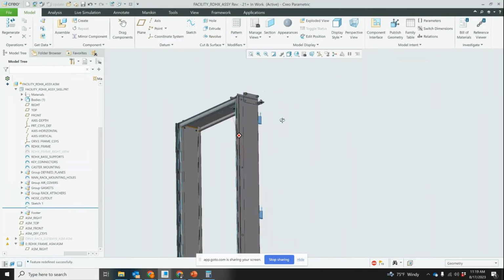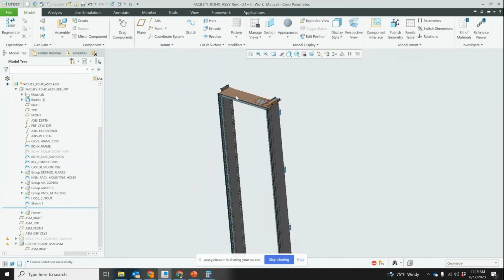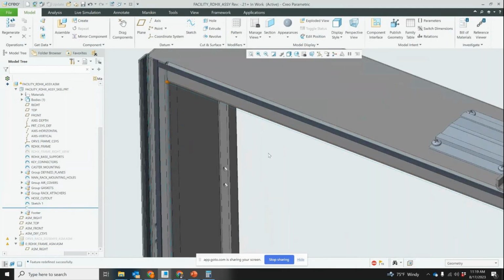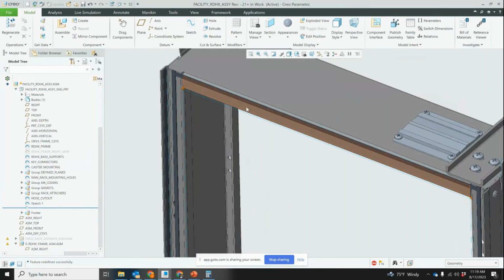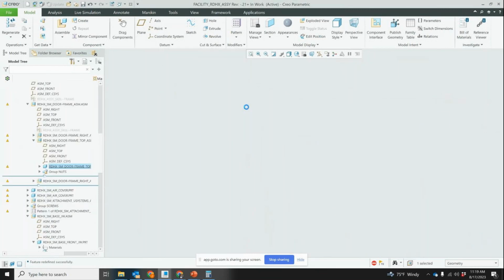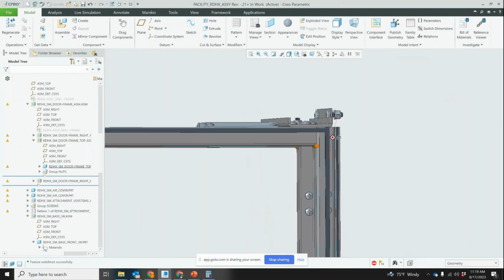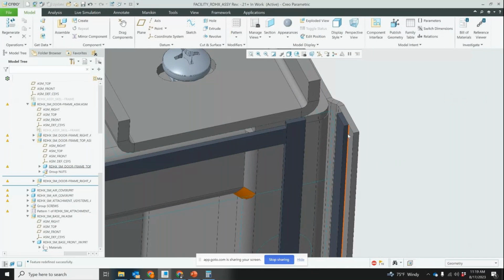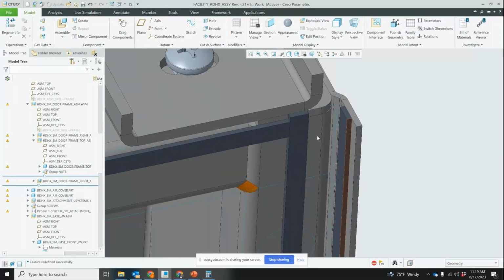Additionally, one thing I wanted to get some feedback on quickly was the gaskets for the door to the frame, as well as the alignment method for the rack that I've chosen here. If you look, you'll see that there's a flange that's bent outwards with a gasket on it. I do understand that if you're pushing a rack onto this face, you might knock this gasket off.